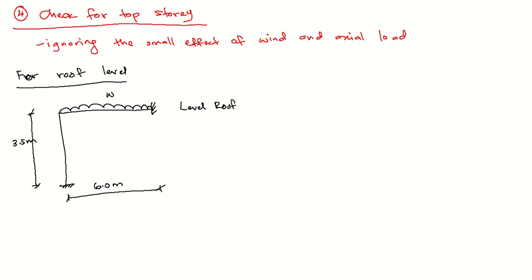For the stiffness of K wall upper, K wall lower, and also K slab, for this case it is K wall lower. We have figured out the K slab from the previous step. K of the slab is 0.744, and K for this wall here, wall lower, for the height of 3.5 meters, is 3.720.